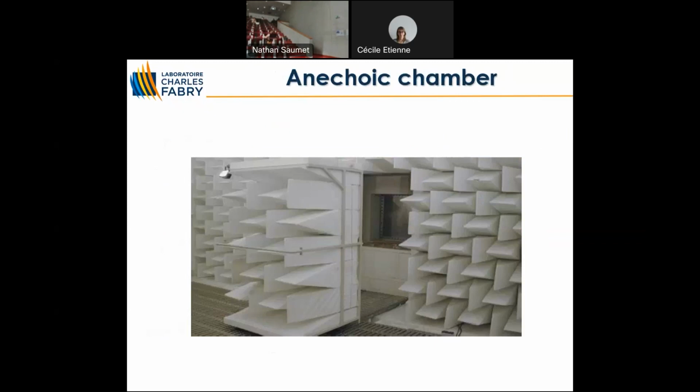And if you go to any concert hall, you will see this kind of structures which are absorbing. And whether you are in homogenization or ray optics, I leave it to you to compute. You have to figure out what's the wavelength in acoustics, 300 meters per second velocity. If you are at 1 kilohertz, you have 30 centimeters wavelengths.